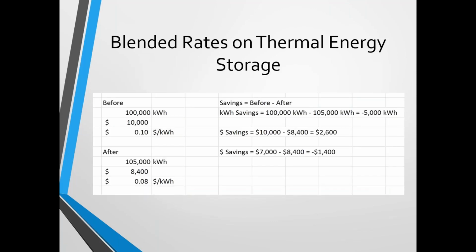So here's a similar example. Thermal energy storage involves making chilled water at nighttime, then you pump it and store it in a tank, and then you have to pump it back. And there are losses while the chilled water or the ice is being stored in a tank, and it could melt. So there's energy that's wasted. It's not always true, but sometimes thermal energy storage will actually use more energy.